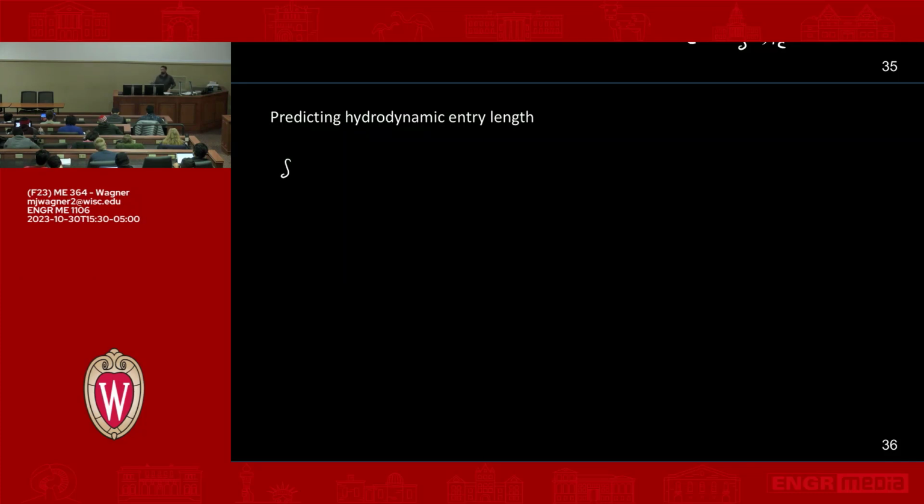We're going to do this again for the momentum boundary layer. We'll get to the thermal, I think, next time. So delta_M for laminar flow. This is our boundary layer model for laminar flow over a flat plate. We would say this is approximately equal to 2 times the square root of viscosity times time. But this goes back to our analog for conduction in a semi-infinite plane wall.